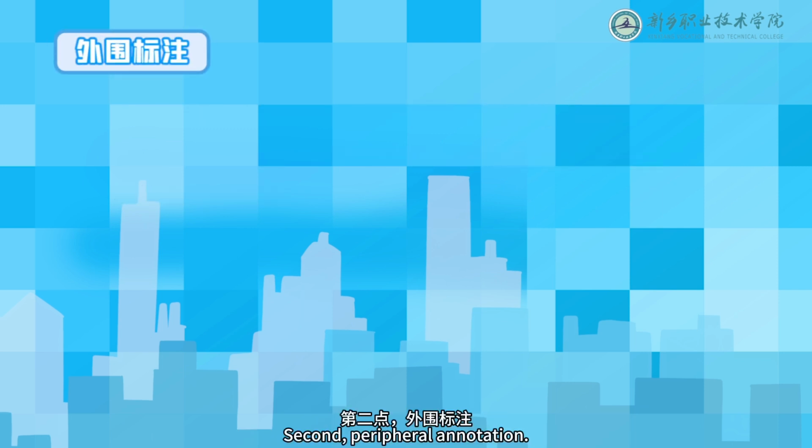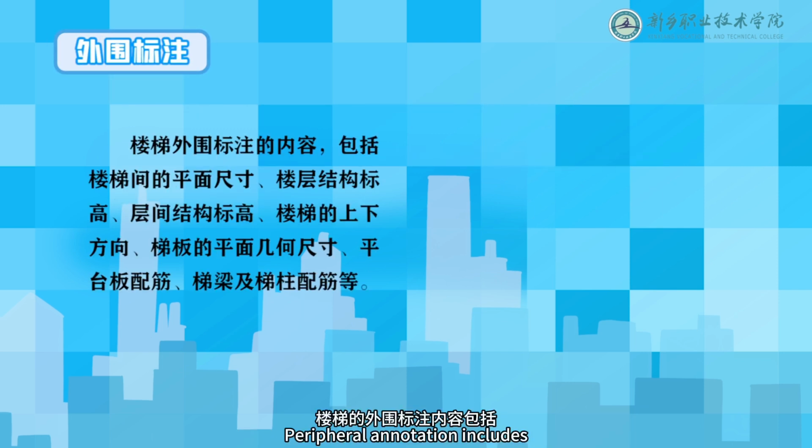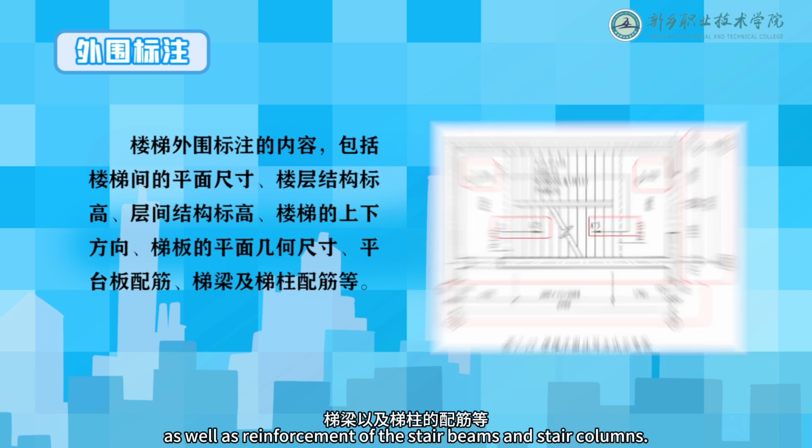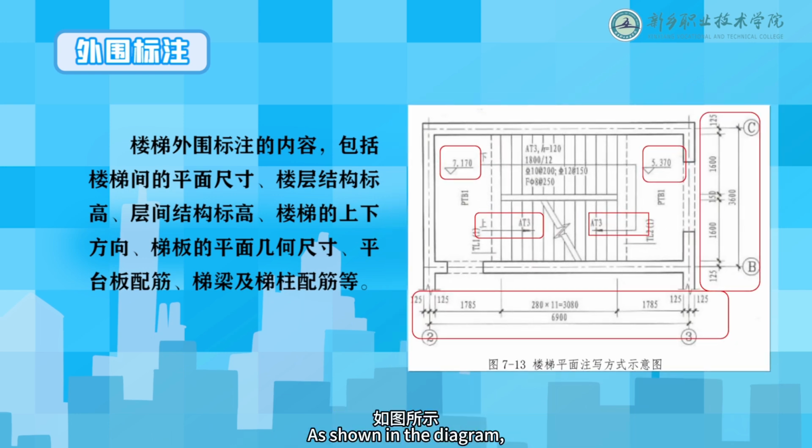Second, peripheral annotation. Peripheral annotation includes the plan dimensions of the staircase, the floor elevation, interfloor elevation, the direction of the stairs, up or down, the geometric dimensions of the stair slab, the reinforcement of the landing slab, as well as reinforcement of the stair beams and stair columns, as shown in the diagram. All of these belong to peripheral annotations.